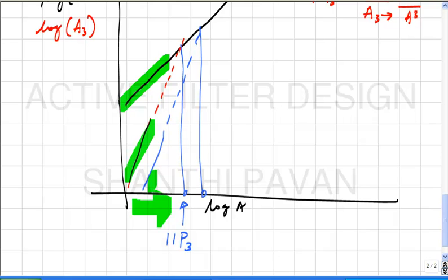See, what is fundamentally happening if you take two tones with amplitude A and frequency delta apart? How long will it take for the amplitude to go to 2A? What is the maximum amplitude that you are putting into the filter? If you had two tones of amplitude A slightly separated in frequency, the maximum amplitude is 2A, correct? So the amount of time you need to wait to hit 2A is proportional to 1 by delta, which is the difference frequency, correct? So if you put in a very small tone spacing, it will take a long time.